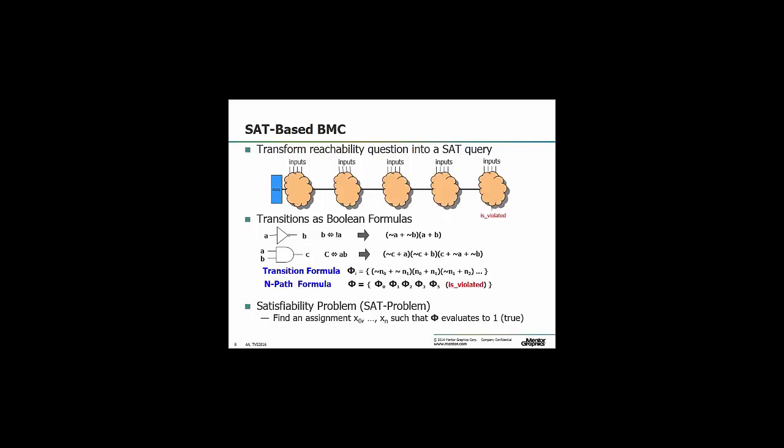In this counterexample, it's actually built on Boolean formulas. It does not have a lot to do with what we have provided as RTL. But this is actually simple. Then you have to map this assignment back to a counterexample. So this is actually where the mystery is coming from. This is the stimuli that the model checker is generating. The SAT solver is generating this assignment, and this is what you are using.